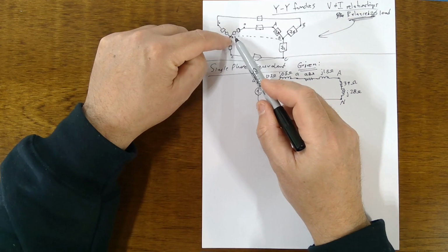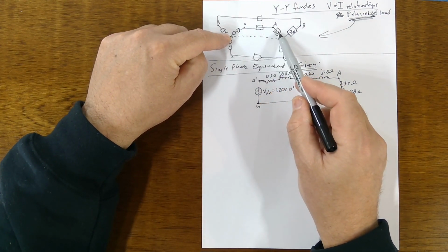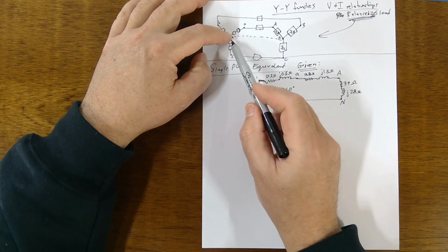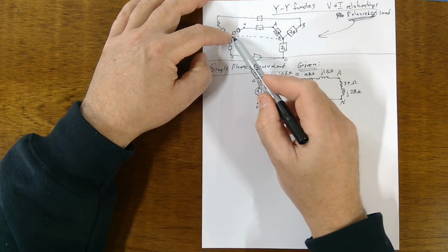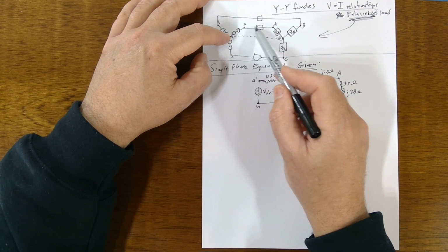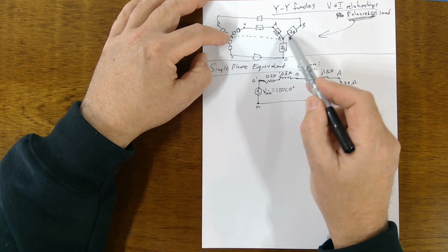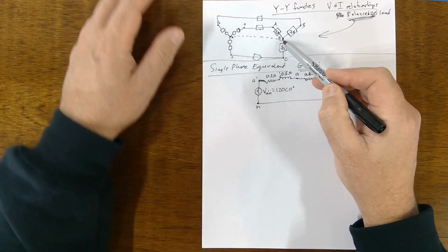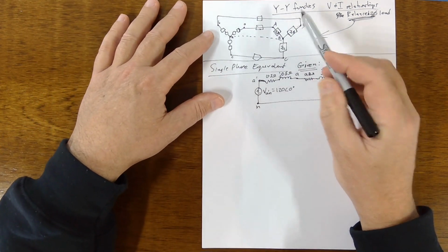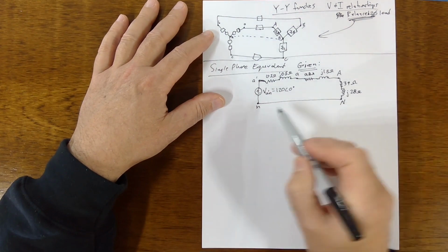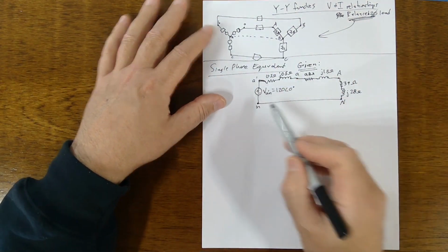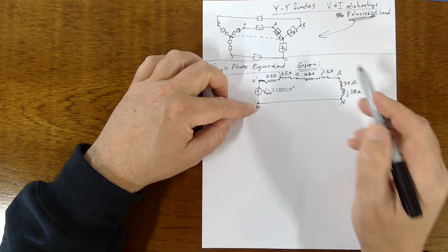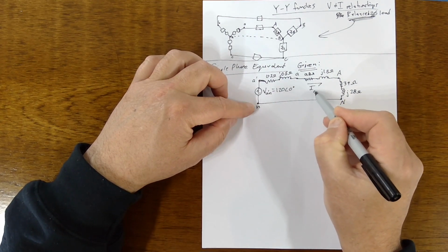But in reality, the return path for this current around the A loop is really going through B and C back to the generator. Let me just say that again. The current comes out here and goes around, gets to this point, and then it goes back through B and C, depending on where the negative voltages are. It's going to go that way. It won't go through here. But we're going to put that in here just so we can solve for the current. So there's a current through here. This is I sub A.